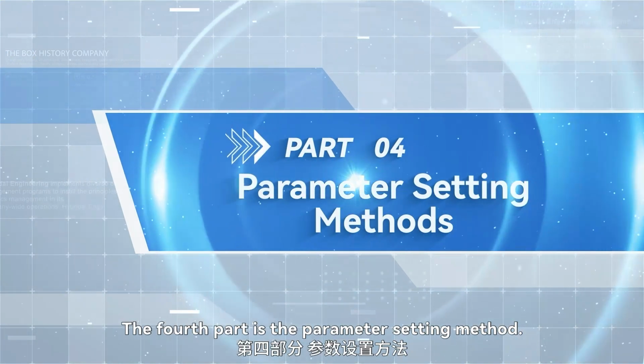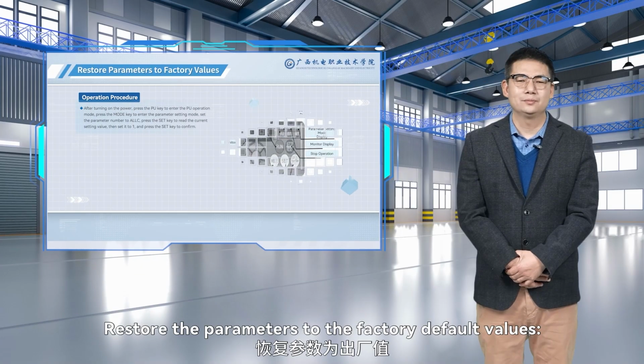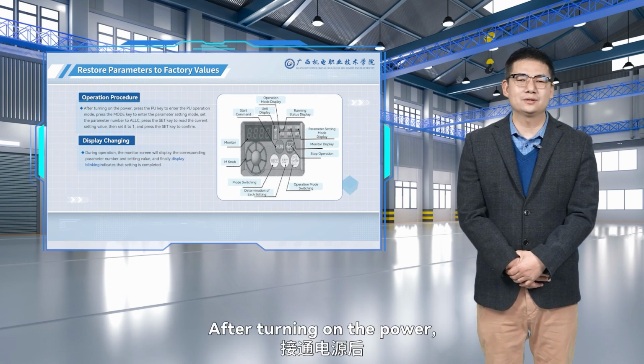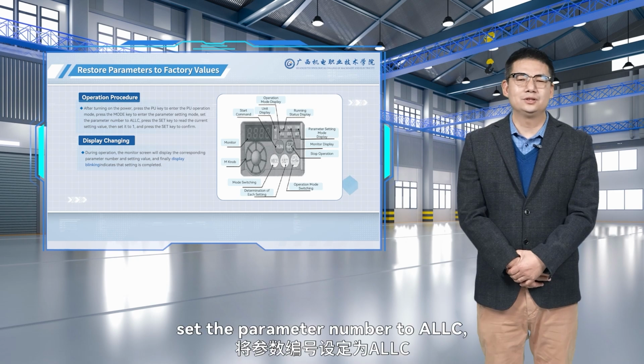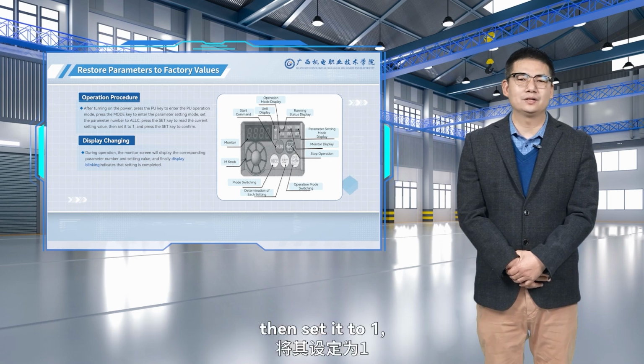The fourth part is the parameter setting method. Restore the parameters to the factory default values. After turning on the power, press the PU key to enter the PU operation mode. Press the mode key to enter the parameter setting mode. Set the parameter number to ALLC. Press the set key to read the current setting value. Then set it to 1, and press the set key to confirm.